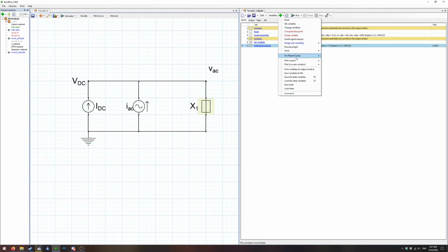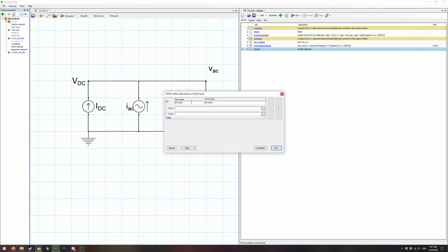Next we're going to be adding in the plot. EIS, impedance. And this is where we're going to be doing something different. So in this case, we're going to be doing curly brackets real VAC over IAC, and then we end the curly brackets, and that's going to be our resistance, and this is going to be our reactance.